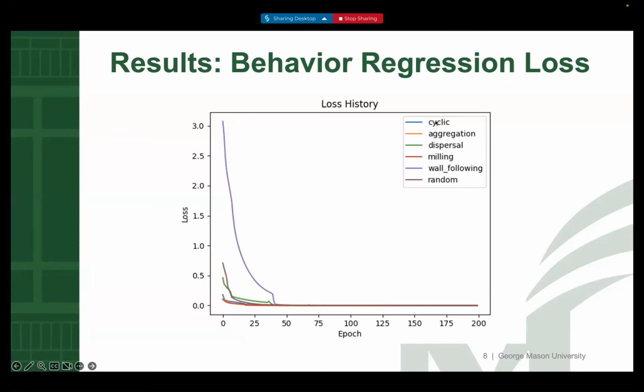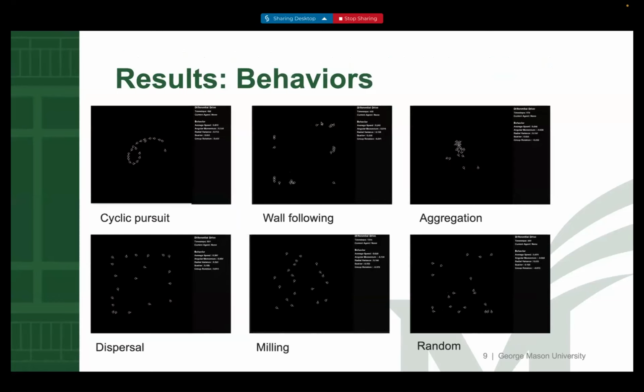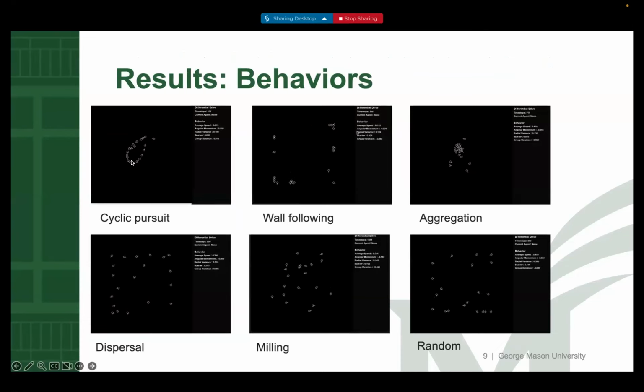These actual behaviors were discovered via the AFRL strategy of using those behavior vectors and evolving them. Then I found strong controllers that way, and trained the spiking neural network via regression for these strong controllers. So these are the output result behaviors. You have the cyclic pursuit, where the robots begin in random positions spread out across the world. Then using just that single binary camera, with no means of communication, they form these useful behaviors as a swarm, using only 5 neurons.